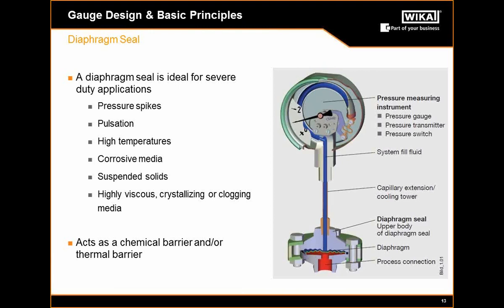The balance of the system is filled with a system fill fluid that is clean, cooled, and would not crystallize or otherwise obstruct the pressure gauge from operating. This is fantastic to use anywhere that you have process fluids that wouldn't be compatible with the standard materials of a pressure gauge. And of course, if you have any further questions on it, I'll be happy to answer those.